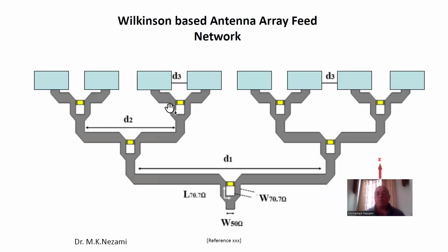If you do a Wilkinson based antenna array feed, that's a little different. Basically in there you occupy more space, but it's the same principle. Like in this case here, it's an equal 1-to-1 power divider. So you get a bunch of those. You just cascade them everywhere, except you add lines to set the spacing so that your splitters are pointing right to the middle of the array.